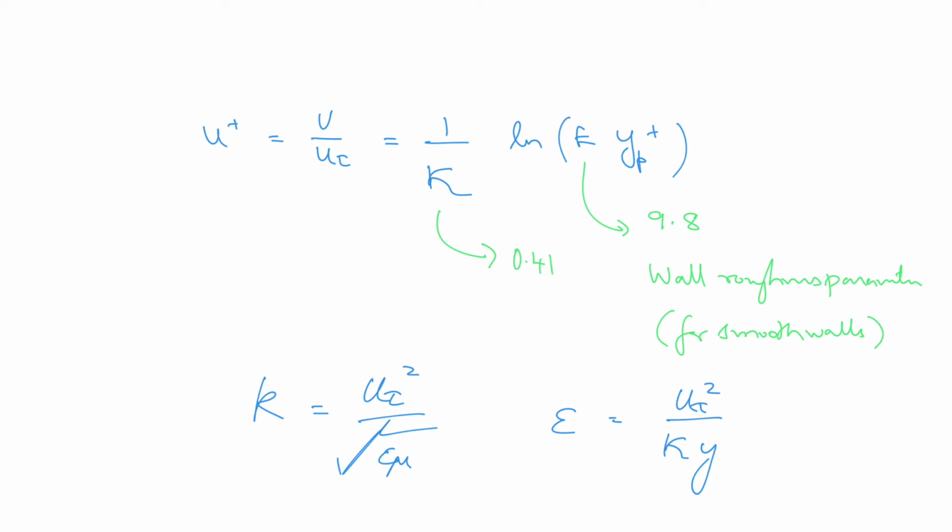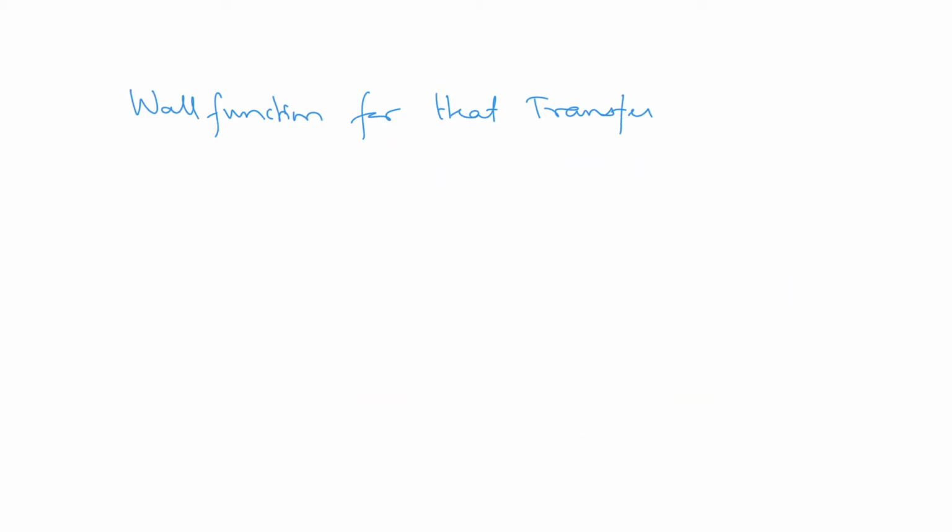Also we should note that this wall function developed for high Reynolds number flow is for isothermal conditions. So if we want to use it for non-isothermal conditions, we have to develop wall functions specific to heat transfer. Again, this wall function is based on the universal near wall temperature distribution, which is valid at high Reynolds number.